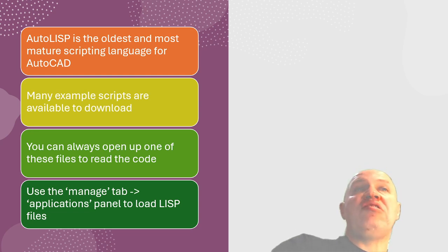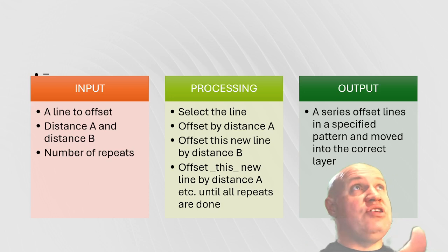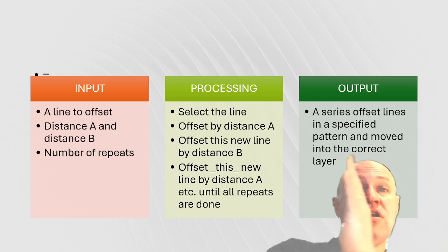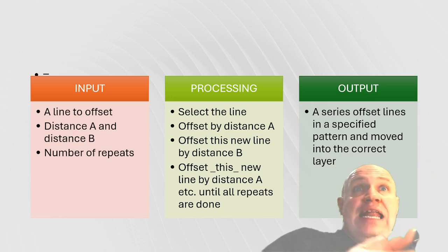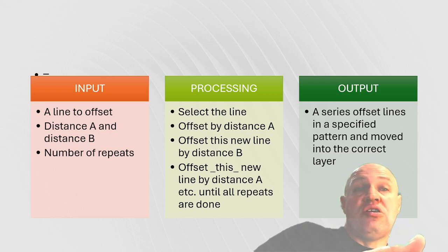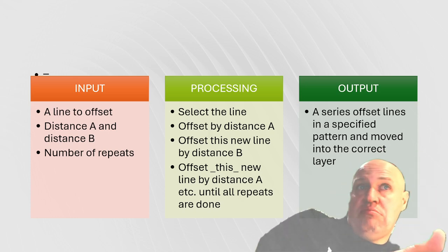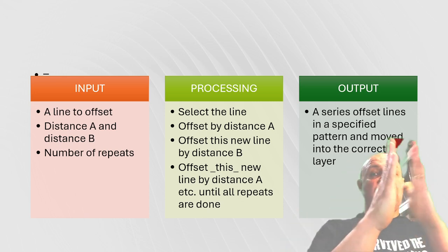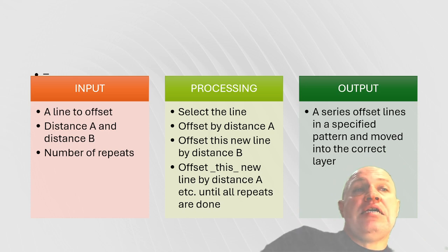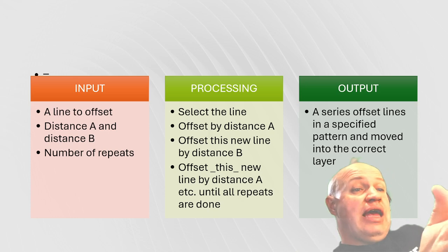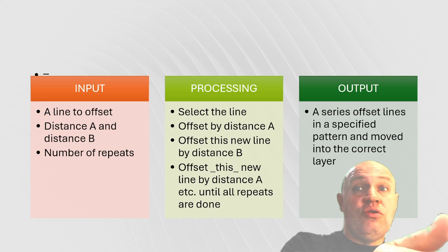A simple tool that I find myself using quite often is a tartan grid. Instead of just having a regular grid where all the lines in the grid are X distance apart, when you're planning as an architect, you sometimes want a tartan grid where you've got wide pieces followed by narrow pieces. So some grids are close together, then far apart, and the next pair is close together. The reason you'd want something like that is you might be working with a structural system, so you might be using load-bearing brick and rooms that can only be a certain size, and you want to work with them like that.